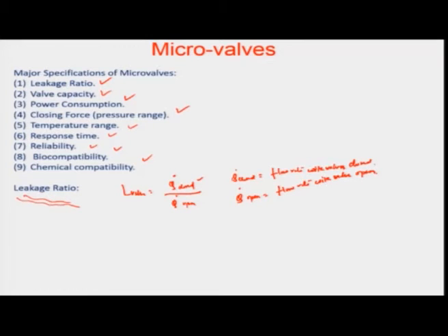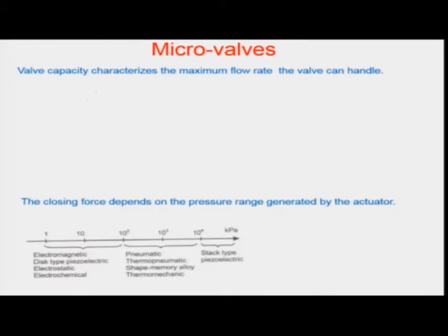The other important issue is the valve capacity, which is actually defined. So, there is a mathematical description of this. It is basically the rate of the maximum flow that the valve can withstand divided by the root of the total pressure difference across which the valve is operating per unit, the density of the fluid, and the acceleration due to gravity product. So, here the Q dot max is the maximum flow rate allowed through the valve, and delta P max is the maximum pressure drop